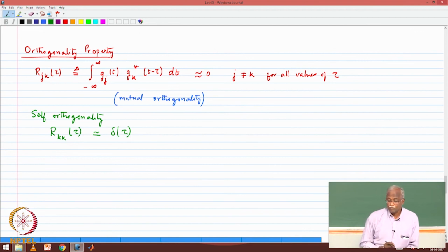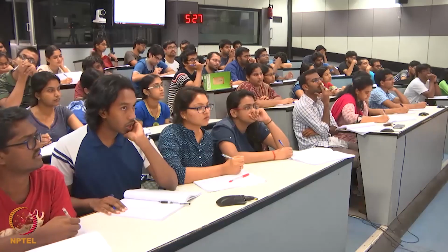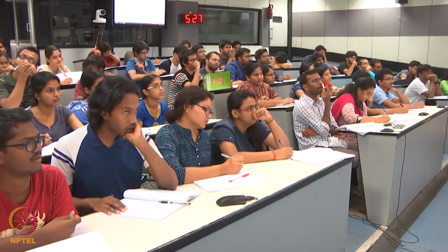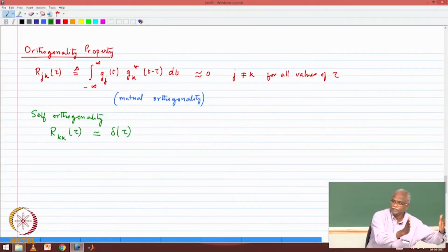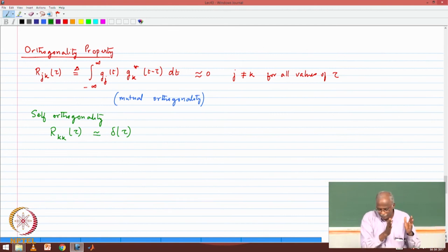If I gave you these two conditions and asked for some candidate schemes for the spreading waveforms, what suggestions could you give me? If you take white noise and take one segment for user k, self-orthogonality is guaranteed, because with white noise you only get correlation at 0 lag.